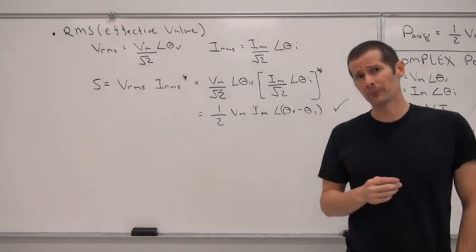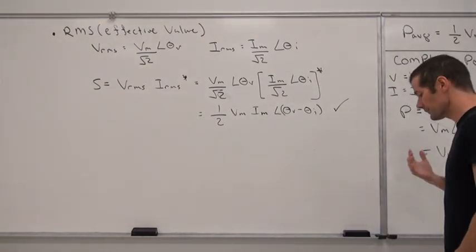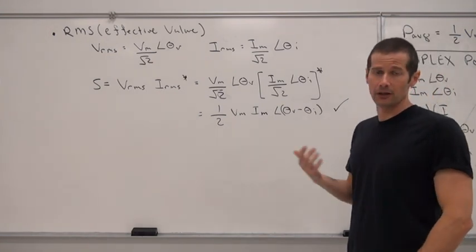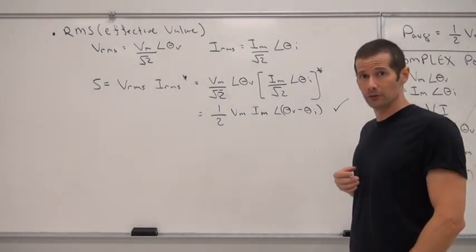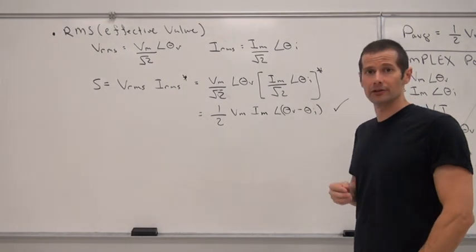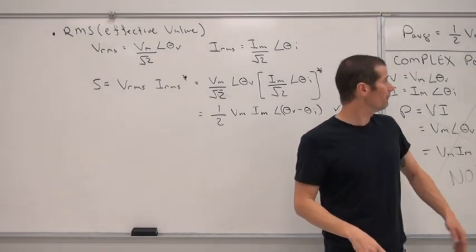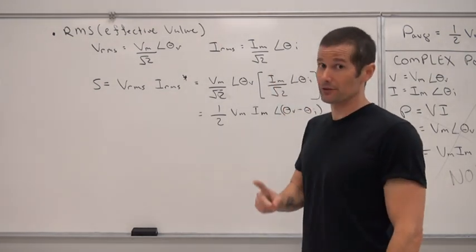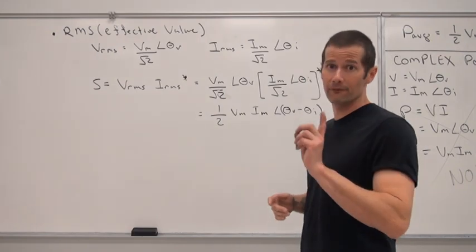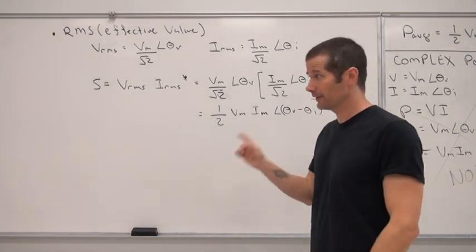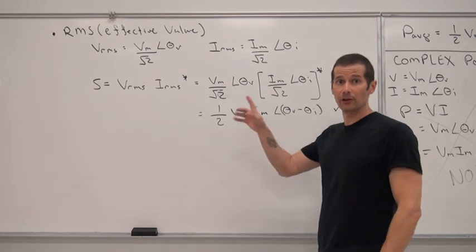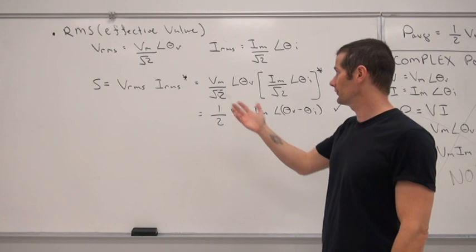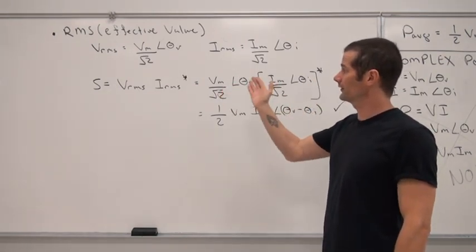So we took our discussion on phasor arithmetic and put everything in terms of their complex forms, whether rectangular or polar, and did our calculations in a more simplistic fashion by mapping back to the real or average power, which was 1/2 Vm Im cosine of theta v minus theta i. But we also want to develop an easier way of calculating these values within the system: V RMS times I RMS.